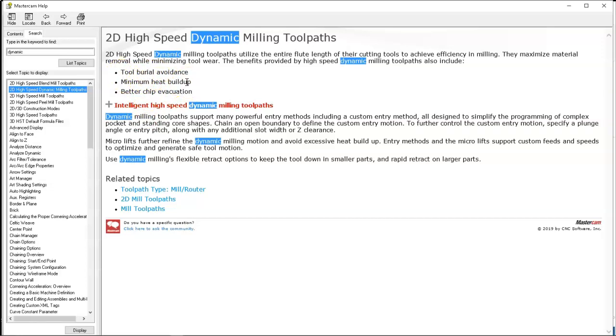So one of the things with any standard pocket is your first pass through the center of any pocket is typically full width, full depth. It is a much higher loaded operation, a much higher spindle load, looking at it from the machine standpoint. So if we can get this engaged and nibble away and not ever see that spike in spindle load, that is going to increase tool life.